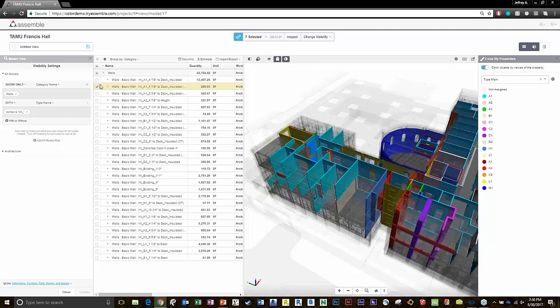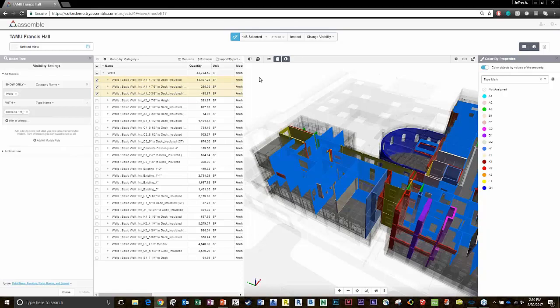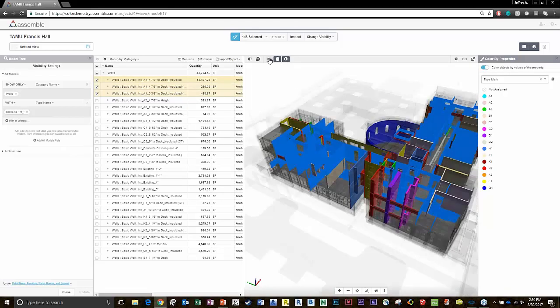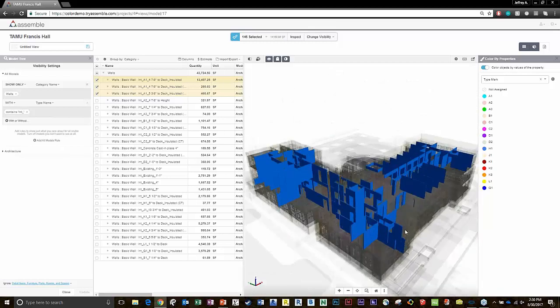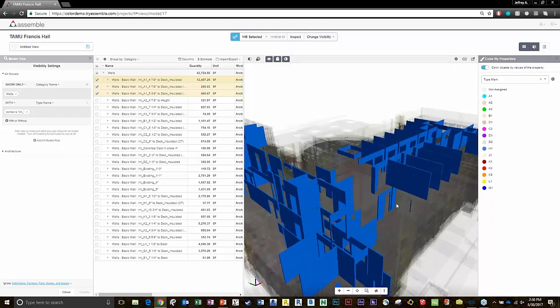You've got your takeoff, so if you want to know all the A1 types, so it looks like all these are A1s with different installation or something, you can select all the A1s. You can see it's giving you 14,160 square feet. If you click the eyeball, you can actually zoom around and get a sense for it, and maybe there's some stuff that's wrong. This is where it's key again.